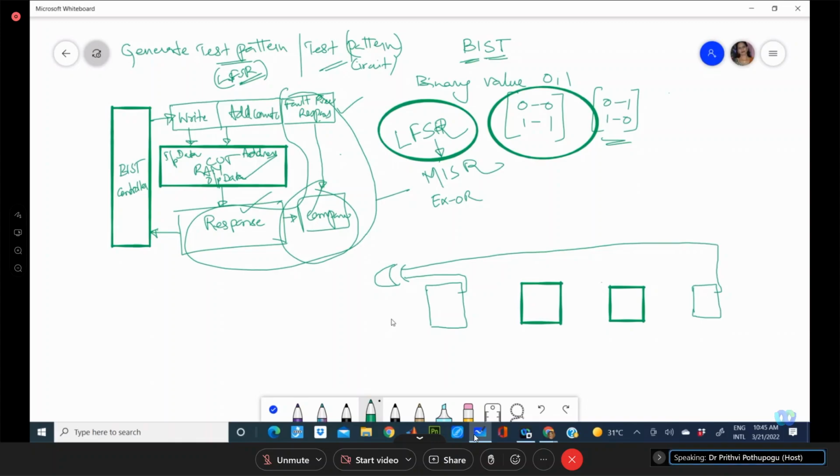Now what we do is, for each stage, or in between each flip-flop, we take one more set of XOR operators in such a way that each XOR operation is provided with the system response and the external test pattern, the pattern with which we want to compare.